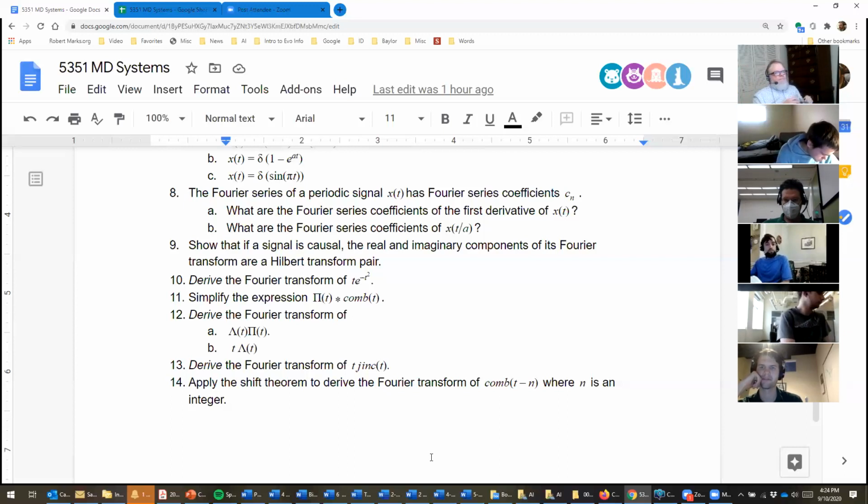It should be the same, right? They're exactly the same. Because the only thing that changes in the Fourier series is the e to the j stuff. All of the other stuff stays the same or can be variable transformed to be exactly the same. So the Fourier series coefficients of the magnified version are exactly the same as the original version. And that's kind of cool. That's kind of surprising. So you need to show that in your solutions.